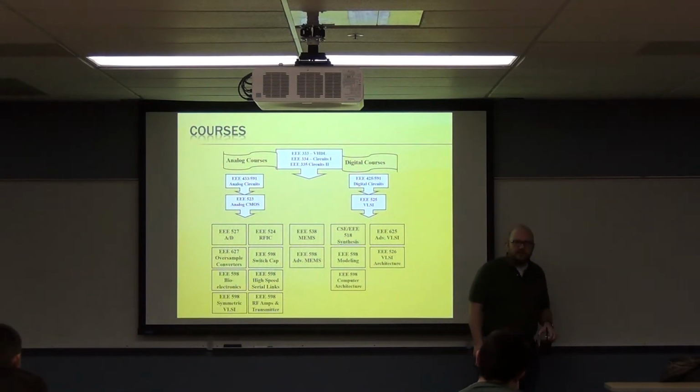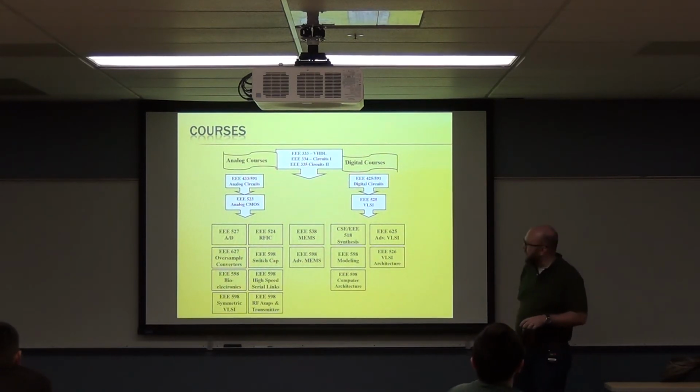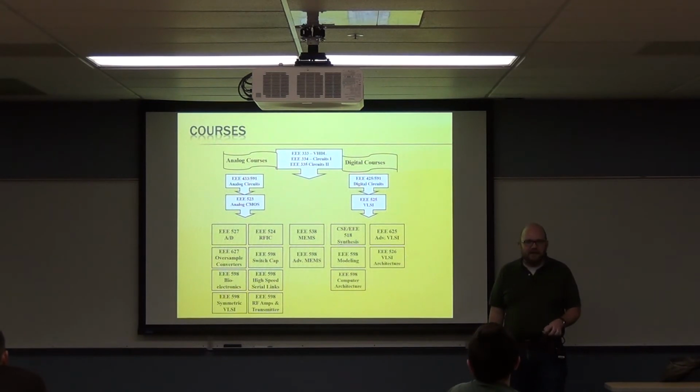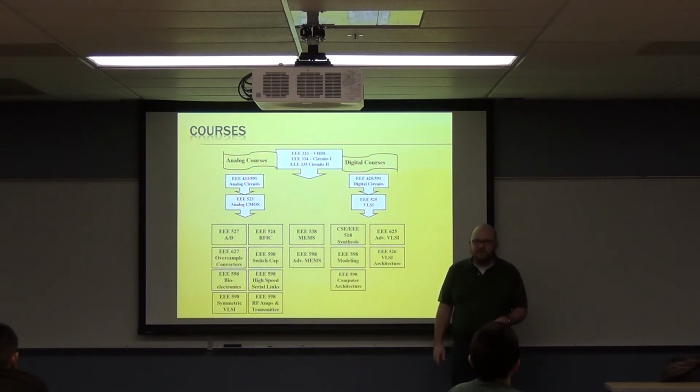Switch cap is, you might think that one way to build an analog signal out of a digital signal is to use a resistor network. Bad news, there are no such things as resistors in integrated circuits. You're not allowed to have discrete resistors, they're gone. So I have to build everything that I used to build out of resistors, out of transistors. Transistors have capacitors on them, at least our CMOS ones do. So if I build capacitor structures, I can re-implement things that look like voltage dividers. And that's what that class is about. And given that it's a whole class, you can imagine it's kind of complicated. Though I have a theory that it's not that complicated if only you just cheat and make it an easier problem.